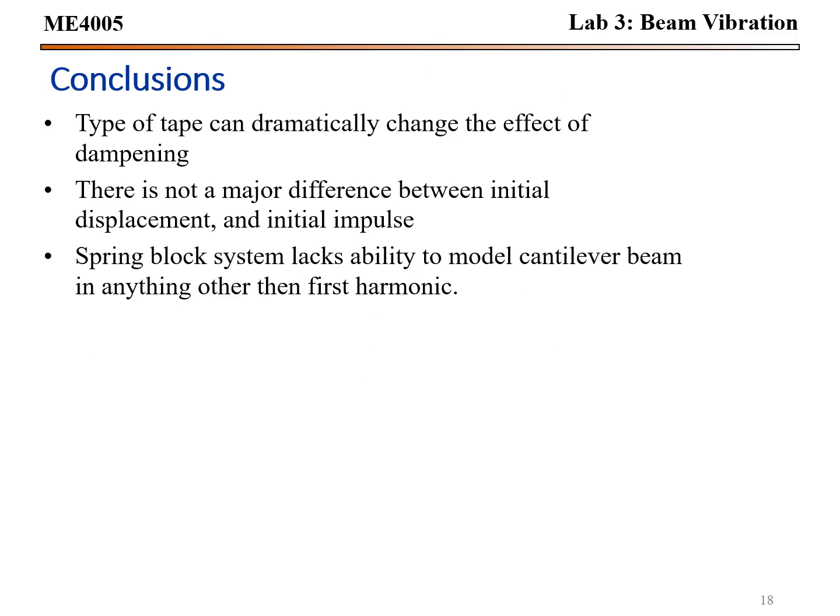Conclusion: the type of tape can dramatically change the effect of damping. There's no major difference between initial displacement and initial impulse, although initial impulse did seem to impart more frequencies into the beam.